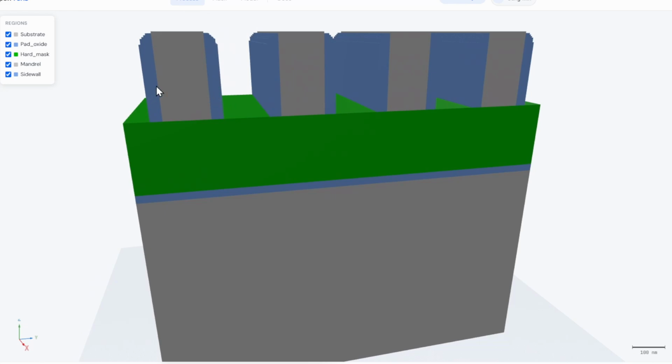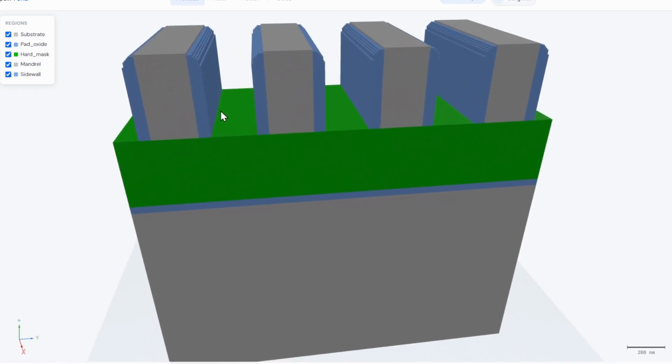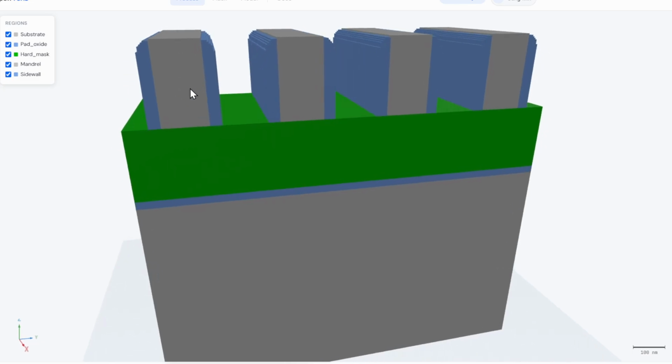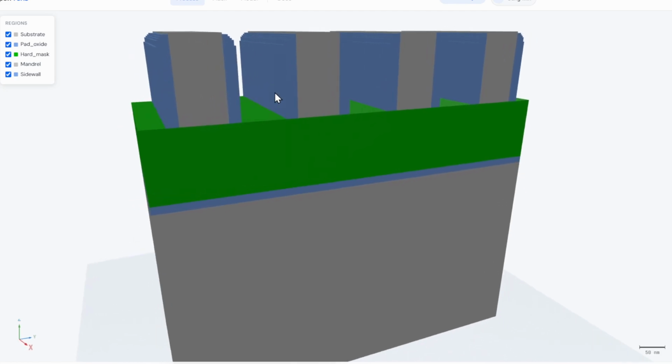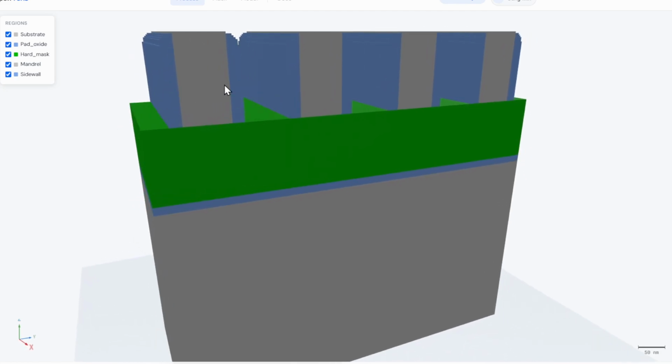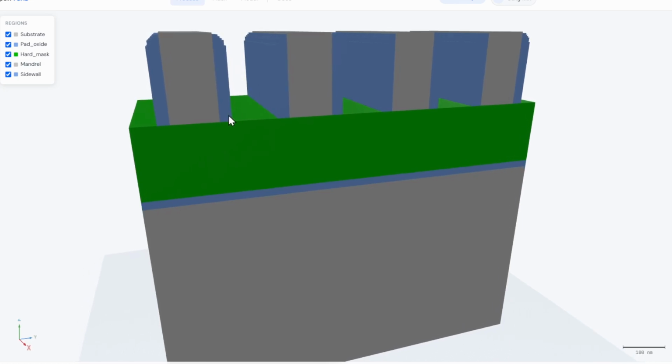So that was 7 nanometer in my case. So now, although we start from quite a thick structure, which is given as mask patterning, the thickness of this sidewall structure is not controlled by this distance, but deposition just precisely controls the distance between these 2 points.